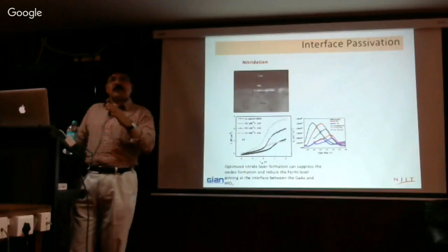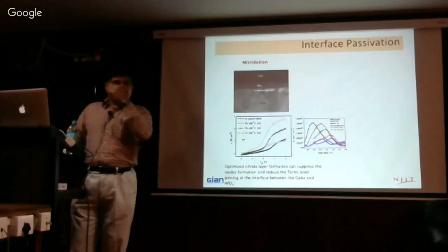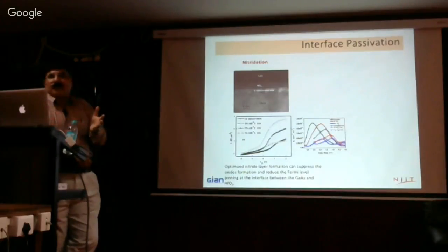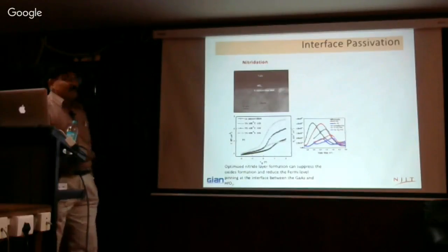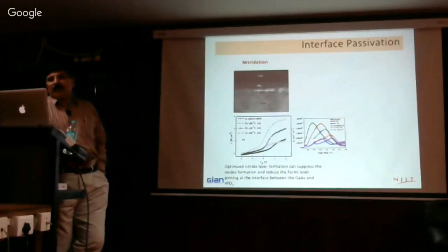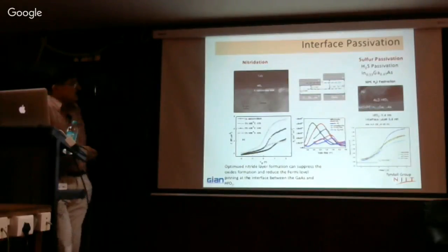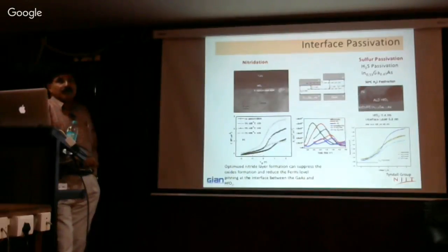And then for the passivation technique, nobody knew what the passivation technique was to make a MOS transistor on a gallium arsenide substrate. So the standard process that we followed for nitrogen passivation and all these things was what they used. Now DIT was coming in at 10 to the 15. That is not acceptable at all, because in silicon dioxide it is 10 to the 10. And then people said, okay, let's do some sulfur passivation. Sulfur has an energy very close to the gallium arsenide surface energy.